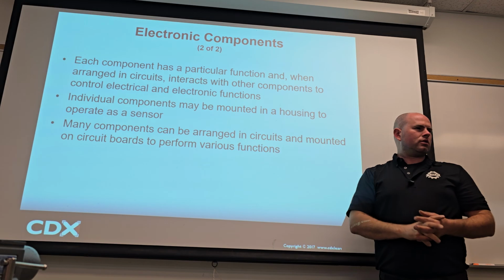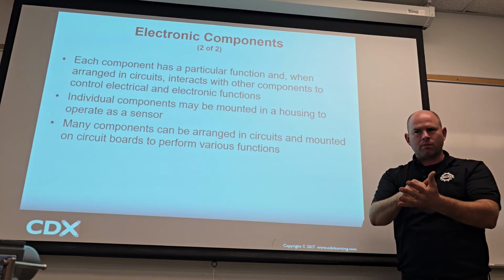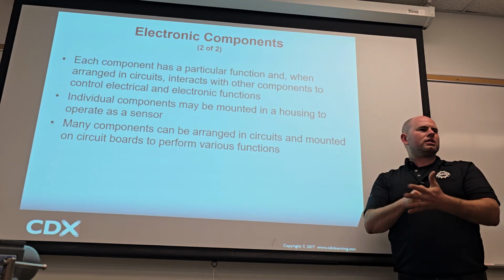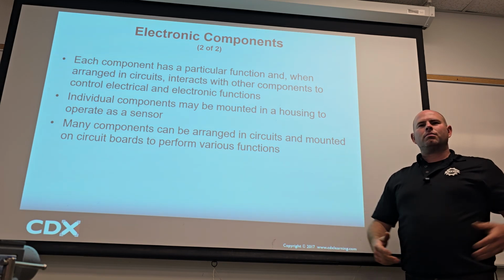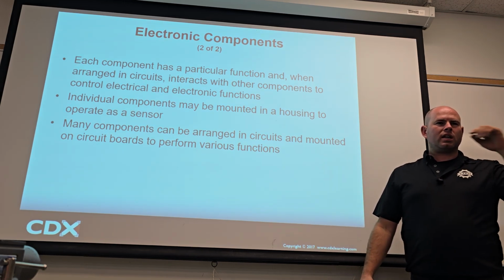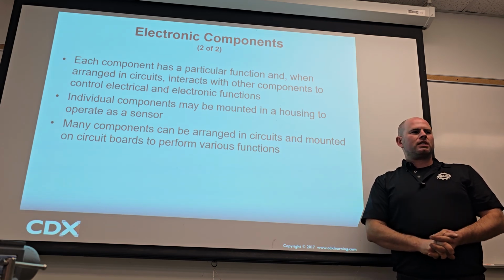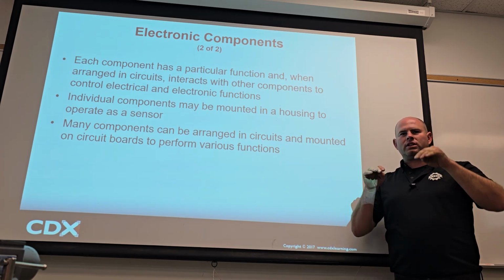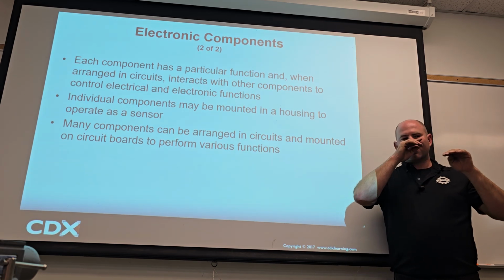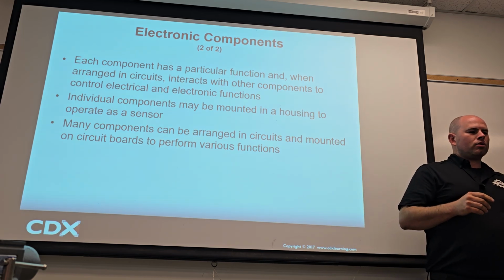We don't change transistors, we replace the ECU. See, you're proving to me that it's a bad ECU. Not just saying, yeah, bad computers do that. Bad computers could cause a check engine light, but so could a chewed wire and so could a burned heating element in the sensor. Make sense? So we got to narrow it down to that level. Don't just think of it as how a computer fails.